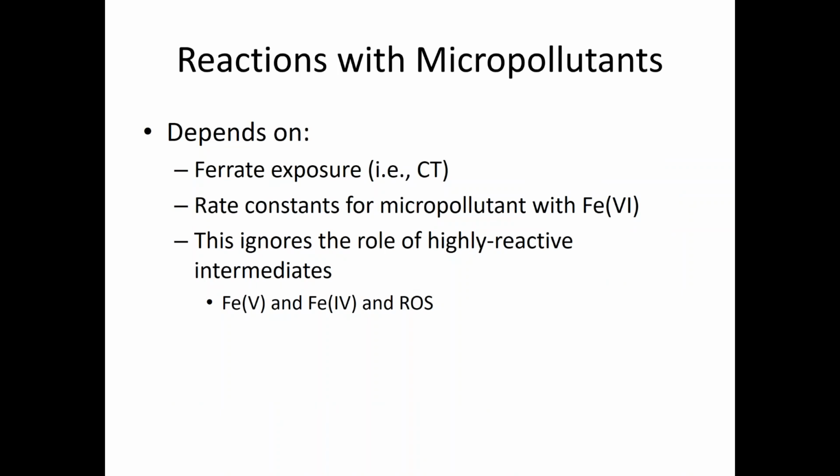And the amount to which you get oxidation of these pollutants in water is going to depend on the exposure, which is quantified in the same way we quantify disinfection, through the concentration times time product, a CT. And that tells you how long the contaminant that you want to remove has been exposed to ferrate and to how high a concentration it's been exposed. And as CT goes up, of course, you get more complete removal.